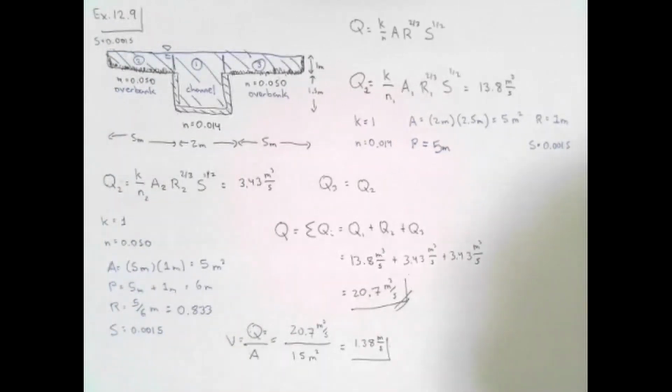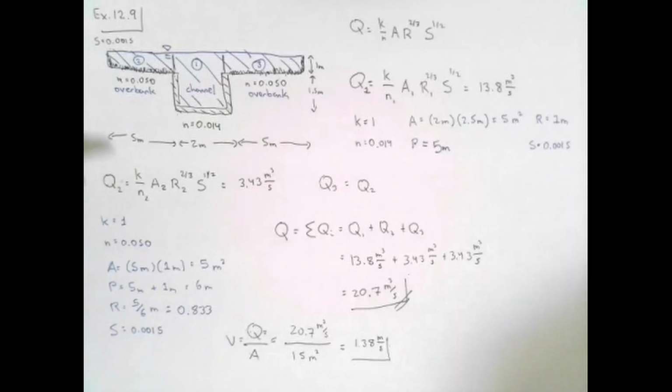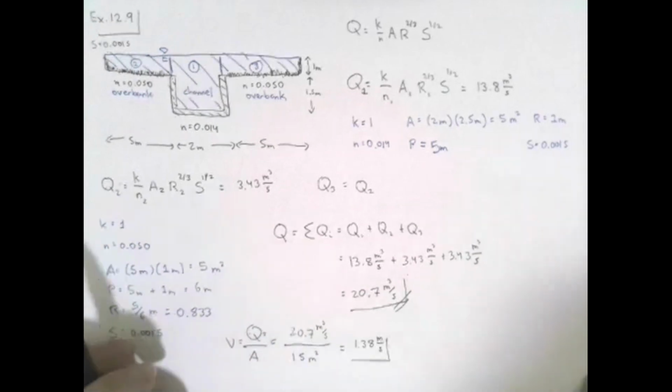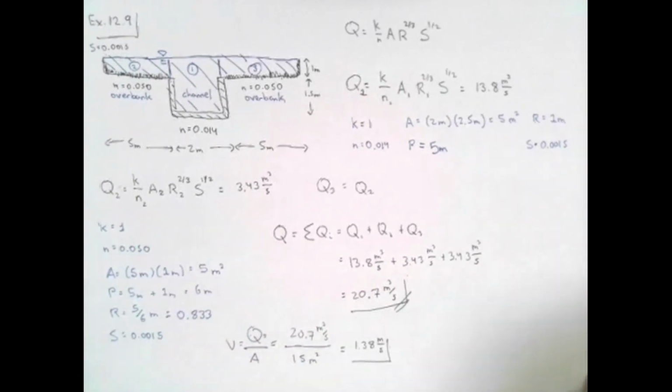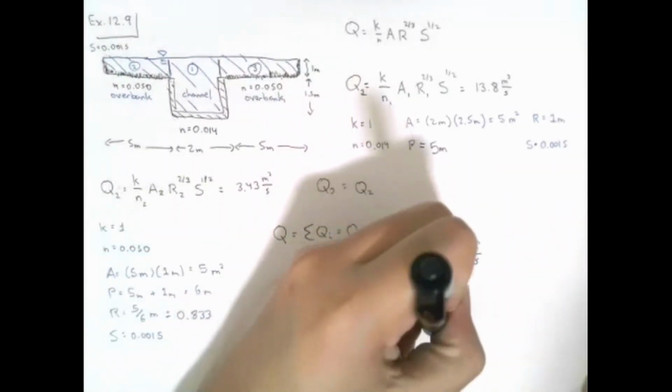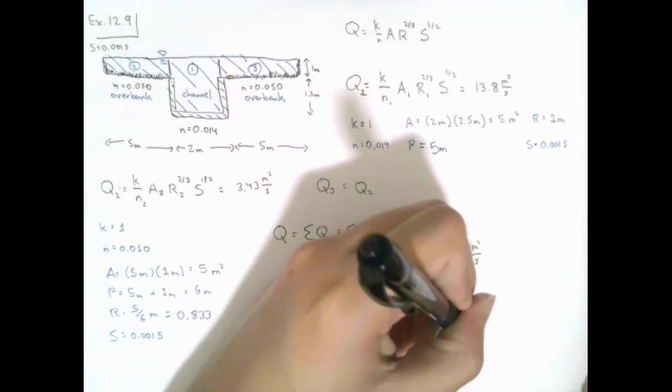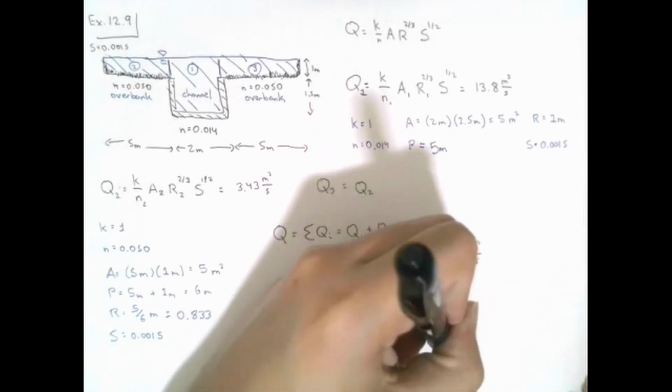But because these are still empirical equations, sometimes we may need to turn to other resources in order to learn how to use Manning's equation. So one helpful tool that I would recommend to everybody dealing with open channels is the HEC-RAS Hydraulic Reference Manual.